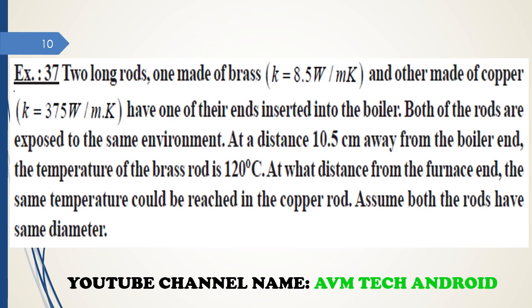As soon as we read the data, we can identify the case, because for a fin there are 4 different cases, and out of all the 4 cases we have to identify which case we have to solve the problem for, because for all the 4 cases there are different equations and different formulas.